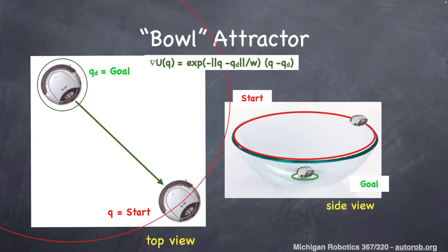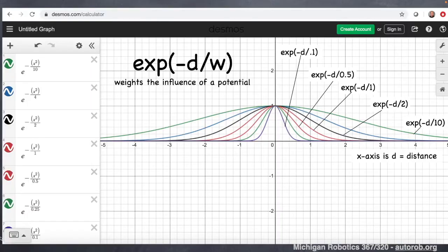So for example, on this slide, we're giving another definition of a potential field through defining the gradient, where you can see we've changed our definition of the gradient now to include this call to the exponential function. And this exponential function is one such that we can control the steepness or the smoothness of its increase by controlling the parameter of this particular function. So this is one approach we could take to controlling the behavior of our robot by manipulating the actual potential field's definition by incorporating these other functions.